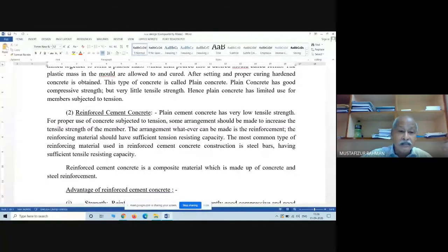Okay. Now, with respect to our neutral axis, the upper part is subjected to compression. So no problem. If the beam is a simple concrete beam with nothing inside, the upper part will be subjected to compression, so it will be safe, no failure. But the bottom part is subjected to tension. Since the bottom part is subjected to tension, and concrete is weak in tension.